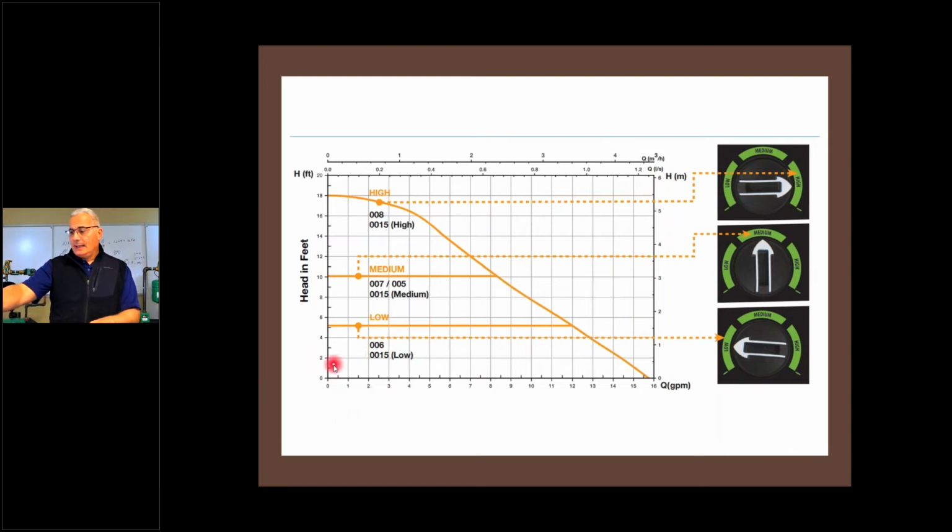So if we're doing that, and I do pick it at medium, so I won't hit 5 GPM, I'll probably end up running up here, probably around 6, maybe a little over 6. So I'm going to move more GPM than needed, but I'll be up here at the 10 foot of head mark. So I will squeeze down my delta T. I won't be maintaining that 20. And as the zones open and close, what'll happen is we'll run along this 10 foot of head line as the zones open and close. Probably over pumping each time by maybe a GPM or more, but I will be squeezing down the delta T because I'll be moving the water faster than I need. So most of the time, I only need 40% capacity, and if I did go for the 5 feet of head, I'll be much closer to the GPM and that 20-degree delta if I ran down there, okay?